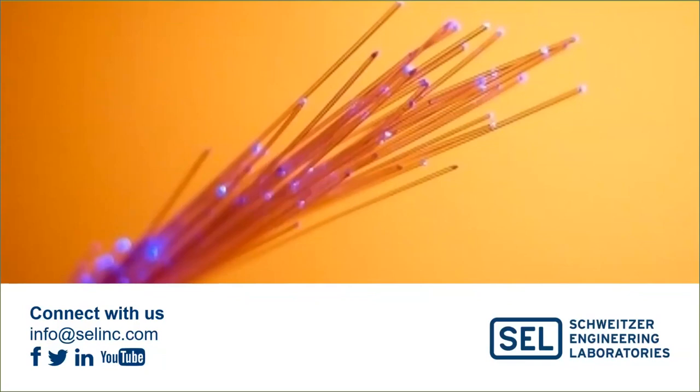The writing is only on one of the fibers. So if you have a real long run and you can't figure out which one is your TX and which is your RX, I'll look at which one has the writing on it, then go to the other end and see which one has the writing, and I know they're the same cable from end to end. I'm not sure that's an absolute you can go off of, but that's been my experience.